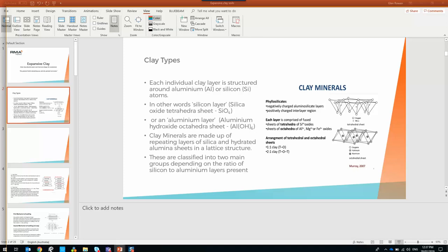So basically I just treat all clays with a YS over 90 the same. You just treat them like they're going to kill your building, and you design accordingly for that. So it's interesting that from a mechanical perspective and for designing footings, that classification goes from very good footings up the top to very bad. And if you're a farmer growing crops, it's the other way around, because the clays' ability to absorb and store moisture is what dry crop farmers want, which is why people are living out on the downs growing wheat and stuff like that.